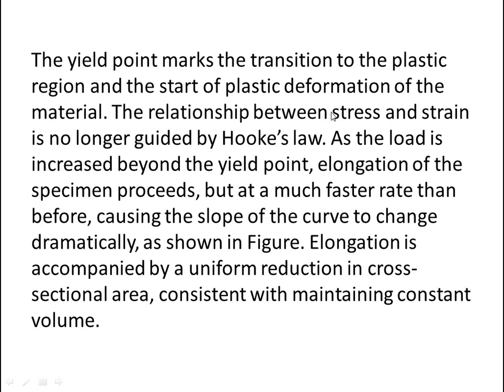The relationship between stress and strain is no longer guided by Hooke's law. As the load is increased beyond the yield point, elongation of the specimen proceeds, but at a much faster rate than before, causing the slope of the curve to change dramatically, as shown in the figure. Elongation is accompanied by a uniform reduction in cross-sectional area, consistent with maintaining constant volume.